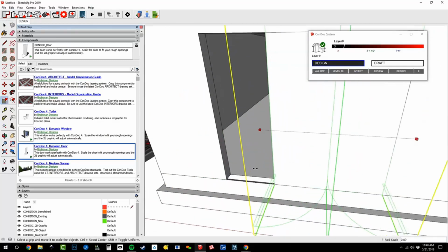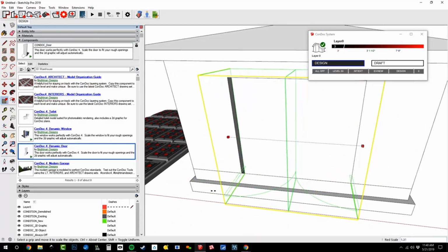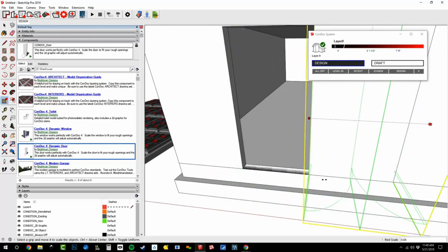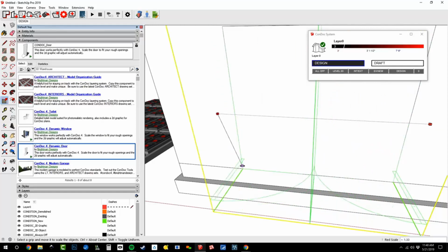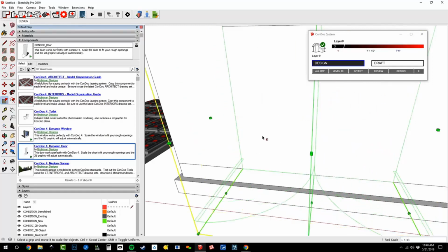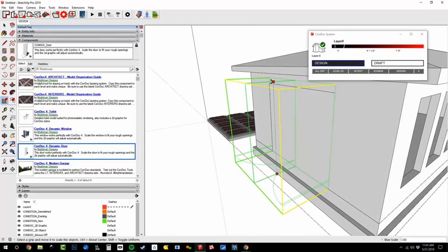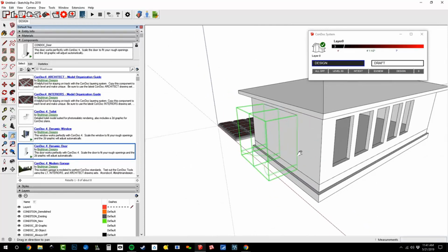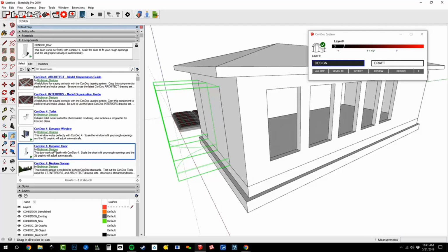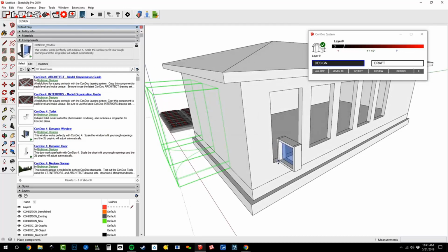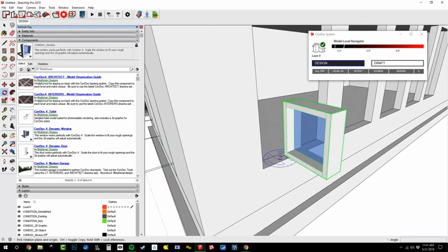And see these ConDoc doors, what's so cool about them is see how those 2D graphics, those door swings, they're distorting. But if I pull it over here and then click, it rebuilds those. So these are like these 3D models that have spreadsheets and rules attached to them. I've already figured it all out for you. All you have to do is just download this ConDoc door, drop it in your model. It's gonna show up correctly on plan. You just stretch it around. Same thing for the ConDoc window.